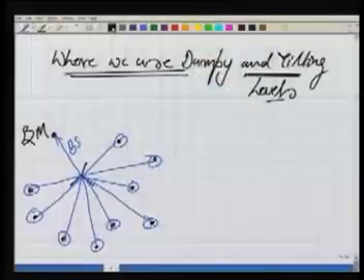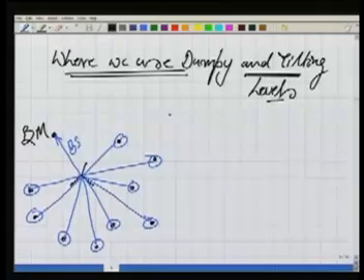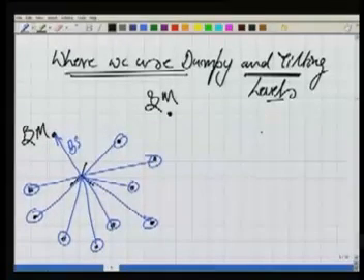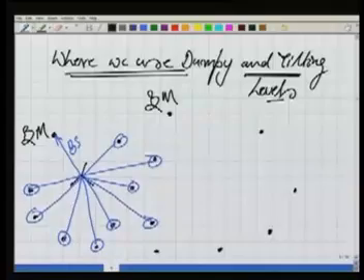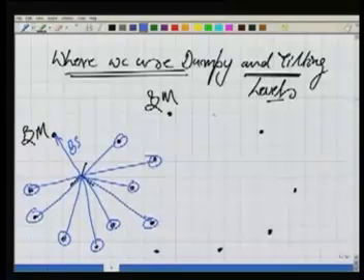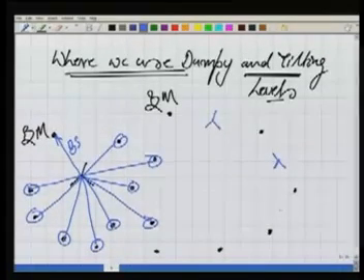In the case of the tilting level, the problem is I have a benchmark somewhere here and I want to determine the RLs of some points which are along a road. It's a linear thing along a road. So I keep my instrument somewhere in between like this.